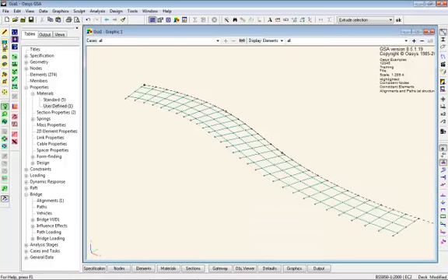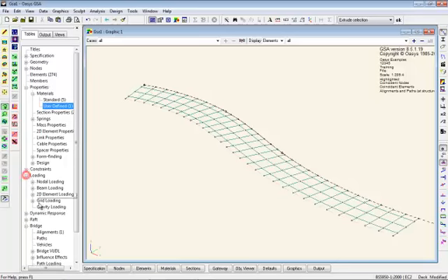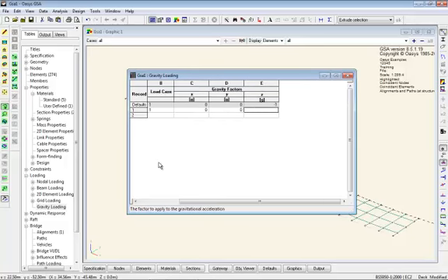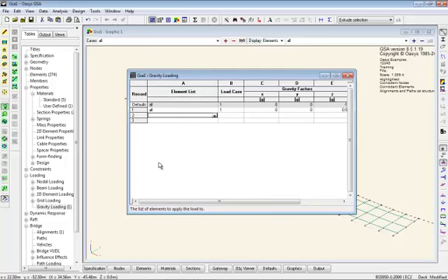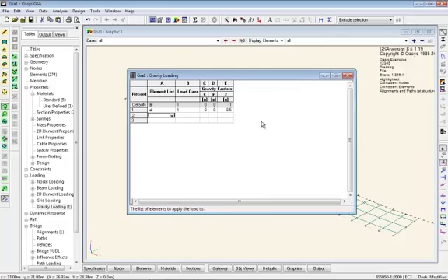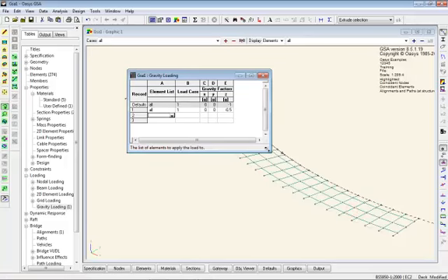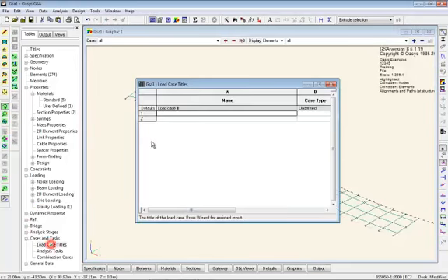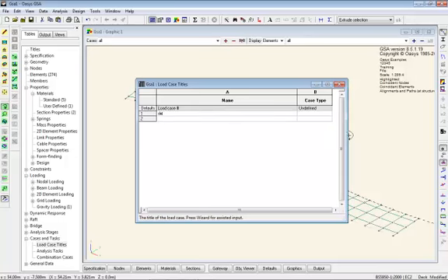I'm also going to now do loading, so just static loading on here. This is going to be dead loads, so all the elements. Case 1. Now I'm just going to take half the weight. Grillages normally take half the self-weight, but this is uneven sections, so this is an approximation. You need to work out a more appropriate factor. Let's give that a name as well. So let's call it dead load.